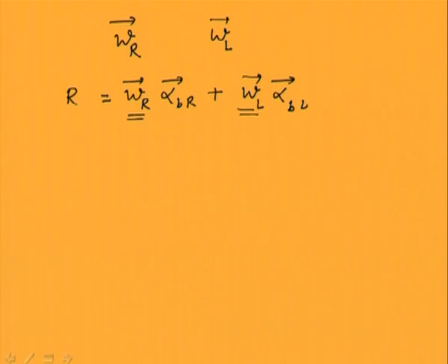Now if we multiply this correction mass with the influence coefficient, plus the other correction mass with its influence coefficient, this quantity is nothing but, because these are the correction masses, they should produce an equal and opposite response corresponding to the case without trial mass, that means minus of R1.